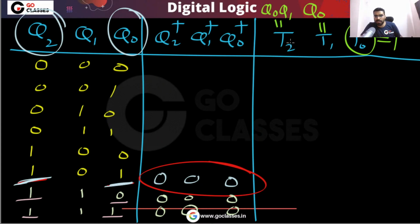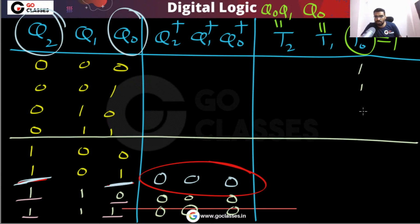Now in the remaining, you can notice this T0 is 1. Because T0 is equal to 1, the output of this T0 flip-flop will toggle in every clock cycle. The next output of this T0 flip-flop will be the complement of the present output. So I can say it will be 1, 0, 1, 0, 1, 0.